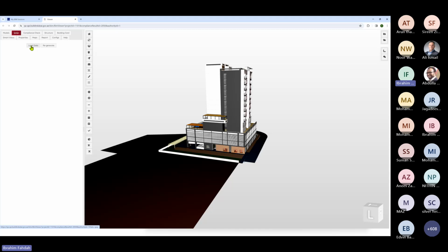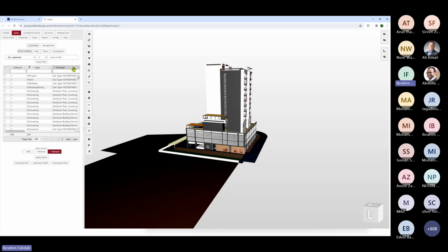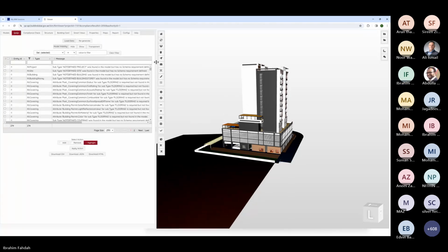And you need to upload the result that was generated automatically by the QA/QC in the background while you uploaded the model and it was processed. The tool will go through all the IFC files and gather any violation in terms of data quality and produce a list that you can download locally. You can produce it in different formats, Excel being one of those formats.